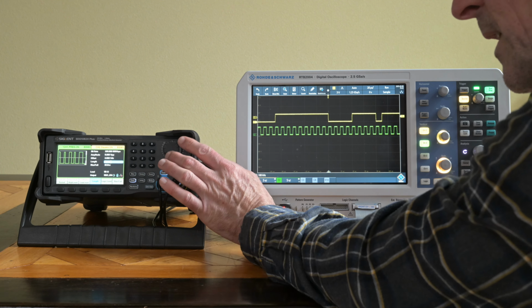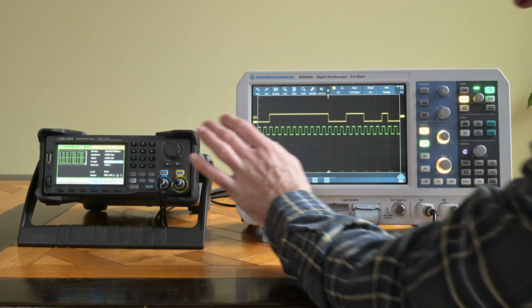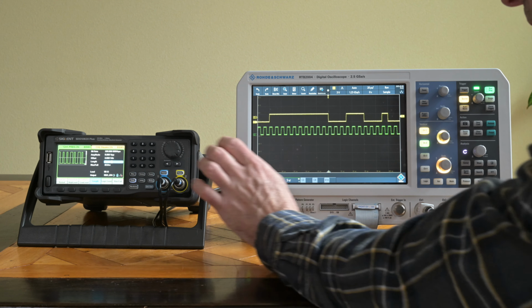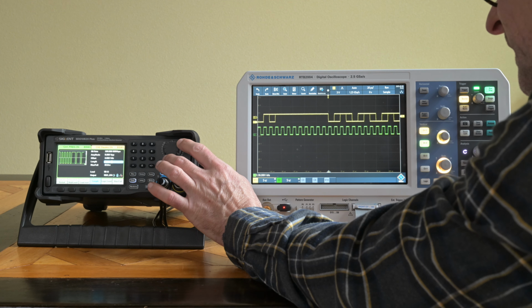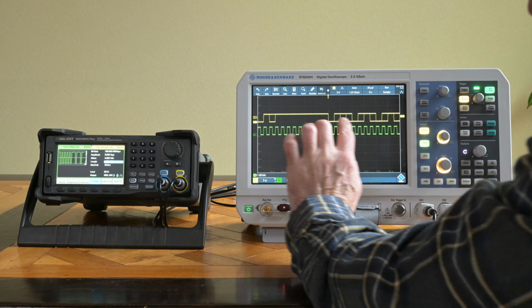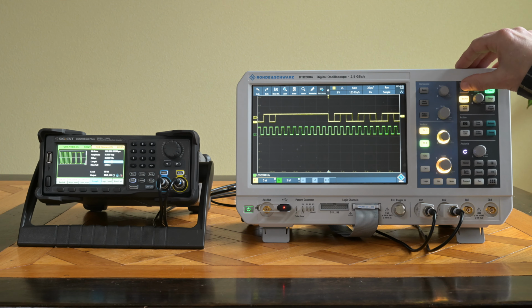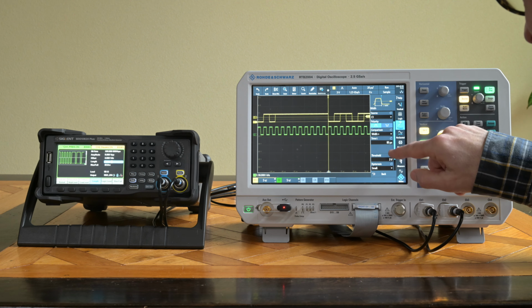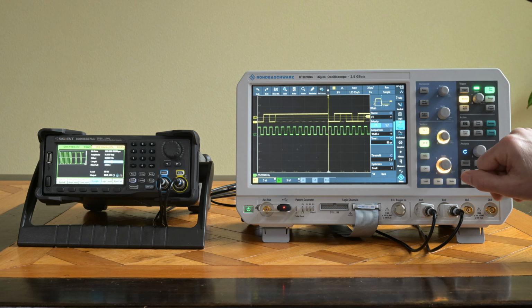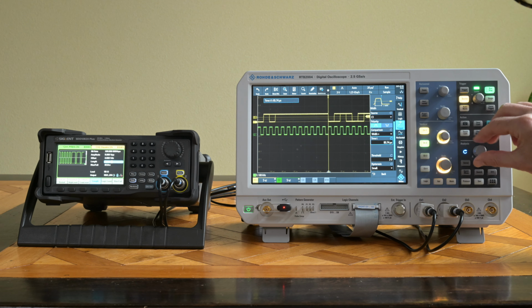And if I go to PRBS 10 patterns, then I should have 10 in a row. It's also finding this. Here 11, I should have 11 in a row. It's actually triggering twice on it. So if I increase a little bit, it only captures the 11, so that is more than 10, right?